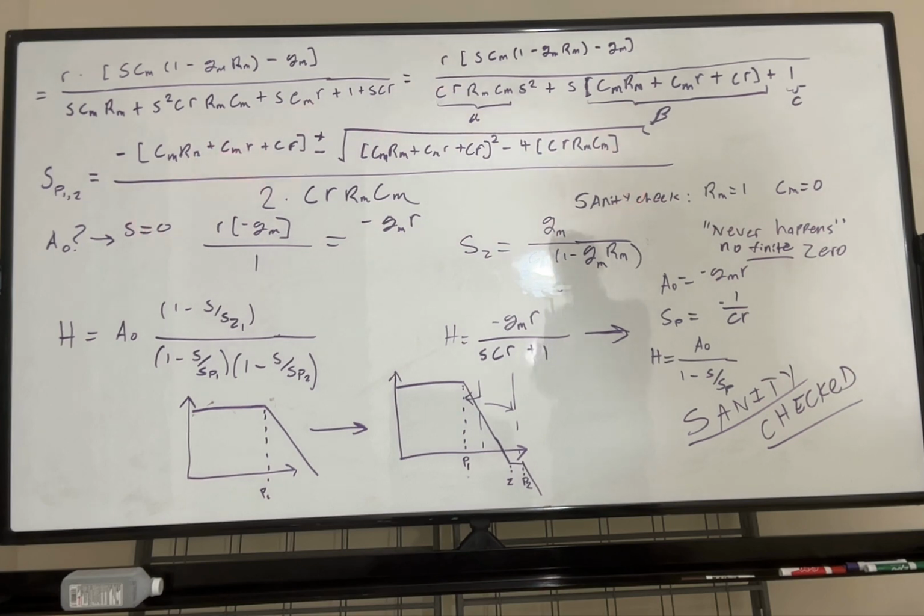The takeaway, though, is that when you have the normal uncompensated one with this transfer function, you just have one pole. And that pole is set by R and C. So you get a simple low-pass filter, right? Now, when you Miller compensate, you introduce a pole and a 0. And you can place the position of the 0 and the poles accordingly. So you get more controllability on when you want your dominant pole and when you want your non-dominant pole. You also get to place your 0.